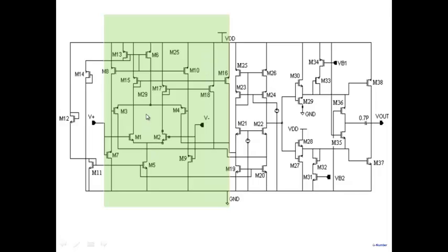What they're trying to do is build the wide swing differential pair that I was talking about. Remember, I was saying that to make it uniform, you have to modify the current sources. Once one differential pair switches off, you have to increase the current of the other. So they've added all this extra circuitry for that, which we have not talked about, to make the performance uniform over the entire common mode range.